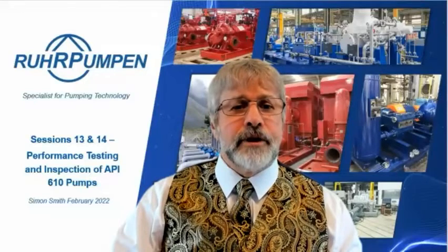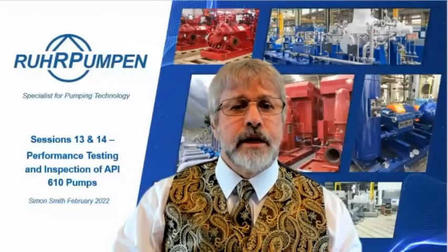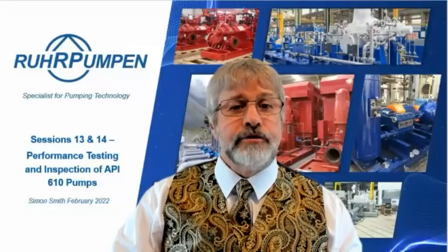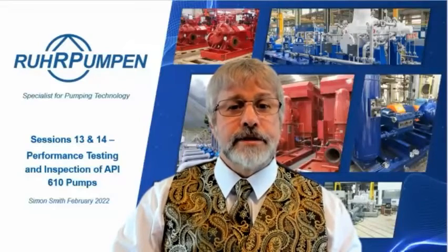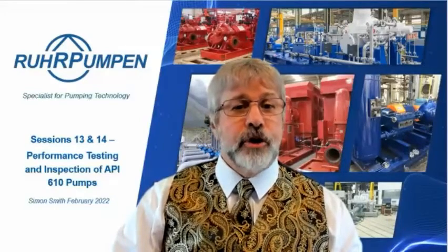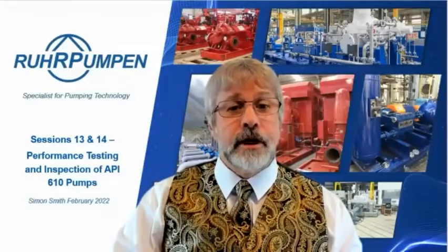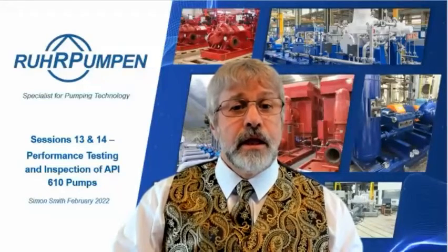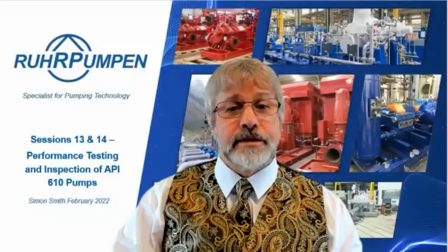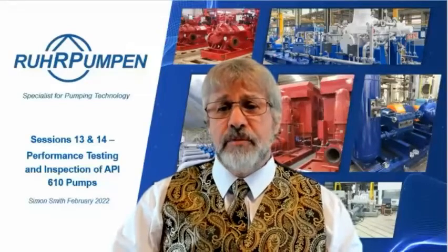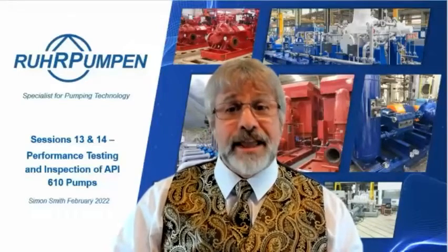Maybe I didn't explain myself correctly, Carlos is saying, do you have any guideline to inspect visually pump internals after test? No material transfer between static and rotating parts, definition of depth of rubbing. I couldn't find anything in API 610 related to this topic. No, I mean, you are looking for exactly that.